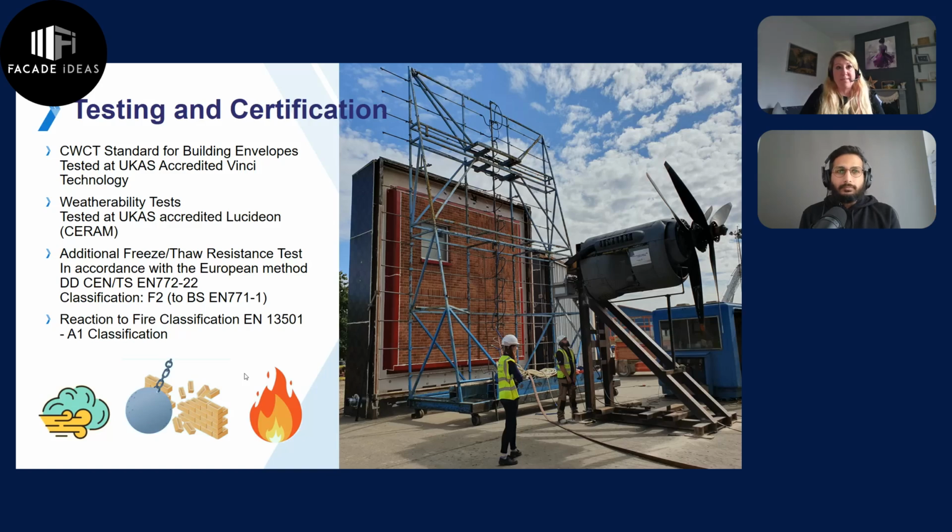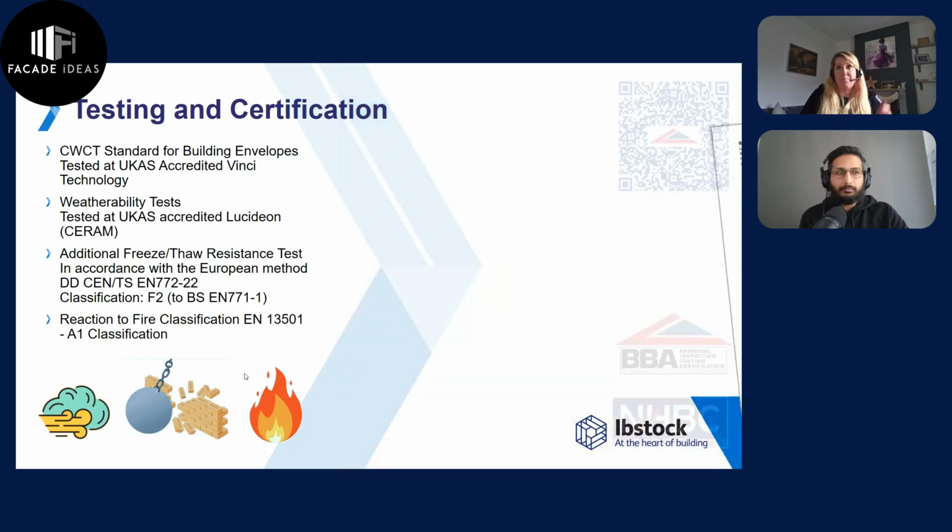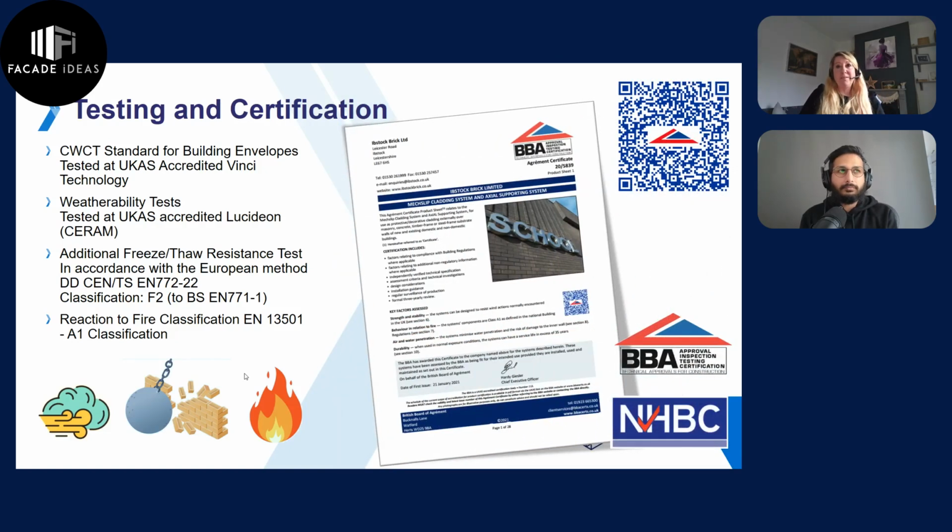Because it's a brick face system, we also test our bricks under a freeze thaw test, which is under British standard EN 772, and we have to classify all of those bricks to F2, which stands for frost resistance classification 2, and that comes under British standard EN 771. The system itself as well is BBA accredited, so again, look for BBA accreditation.